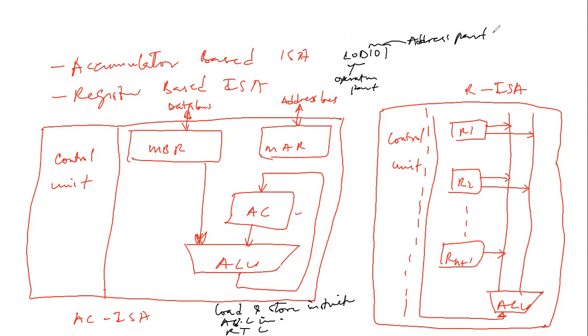So when the instruction is executed, the contents of memory at address 101 are loaded into the accumulator. Same thing for STO 101, for instance. It will store the value of the accumulator into the memory word at memory location 101. So to read a specific word in memory, its location must be specified. And this has to do with the addressing methods we mentioned earlier, okay?